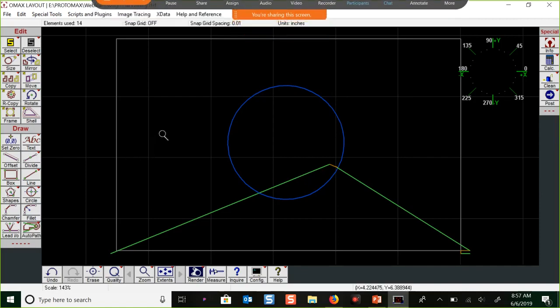Okay, so I went ahead and assigned my quality for etching. Your lines are now gray, and it's the same thing. With the ProtoMAX, you've got to assign your speed quality, and your speed quality is going to be from 0, which is going to cut the same as you are now, to 100, which is going to zip through, which allows the ability to etch the material. The best material that etching is going to do on the ProtoMAX is metals, hands down.